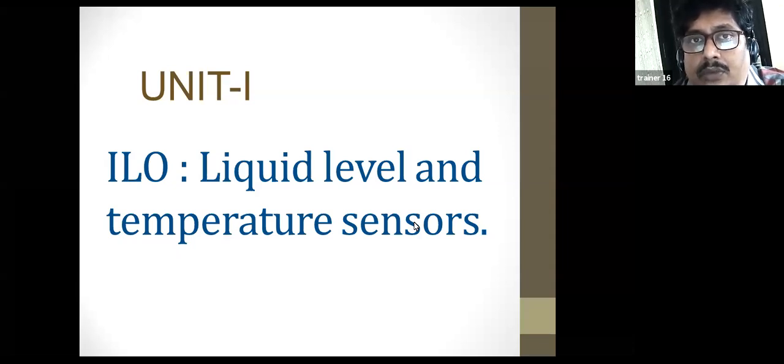And then next we discussed the Bourdon tube pressure gauge. When pressure is sensed, the Bourdon tube expands. When the pressure is less, the Bourdon tube contracts. Thereby, with a rack and pinion arrangement, the needle or pointer moves on the scale, which represents pressure. So these are the topics we discussed in the last class.